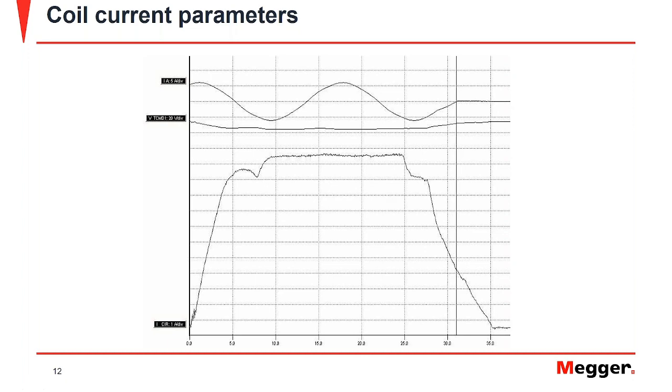And this is a real life measurement, by the way. It's taking the breaker at least 31 or 32 milliseconds to operate, which is for all the breakers, or even I think modern ones now, it is still the real time of them.